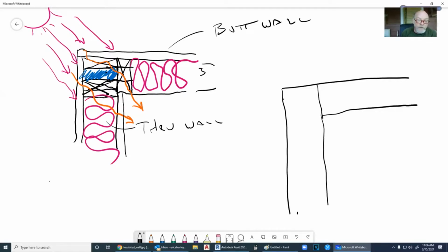So, all right, let me go back, and we got 3.5 here. We said that this was 4.5 here, meaning that we have 1 inch of space. And if I'm getting anybody confused, please tell me. I have 1 inch of space between the edge of this stud and the edge of this stud. So if I were to put this piece of drywall on first, which is 1/2 inch, then I have only 1/2 inch of space here to nail this piece on, which is problematic.